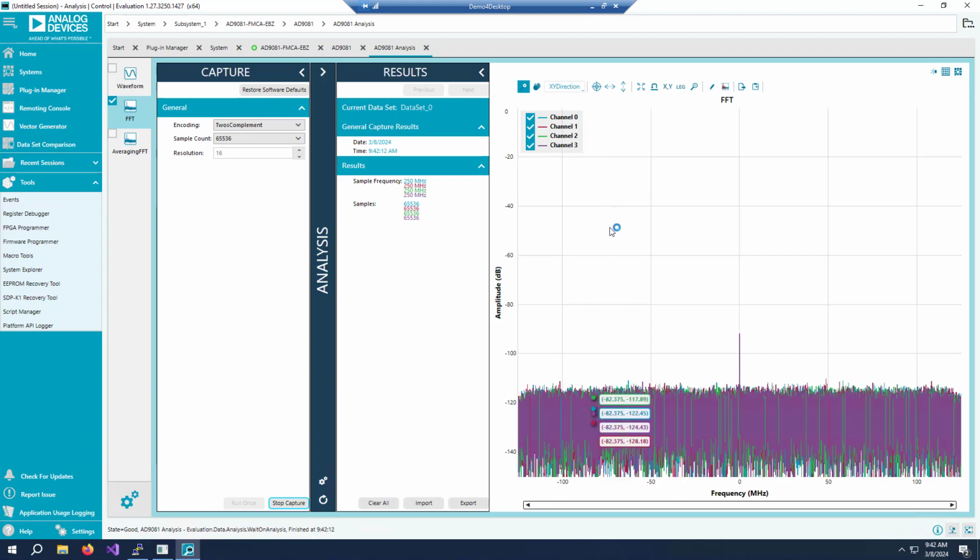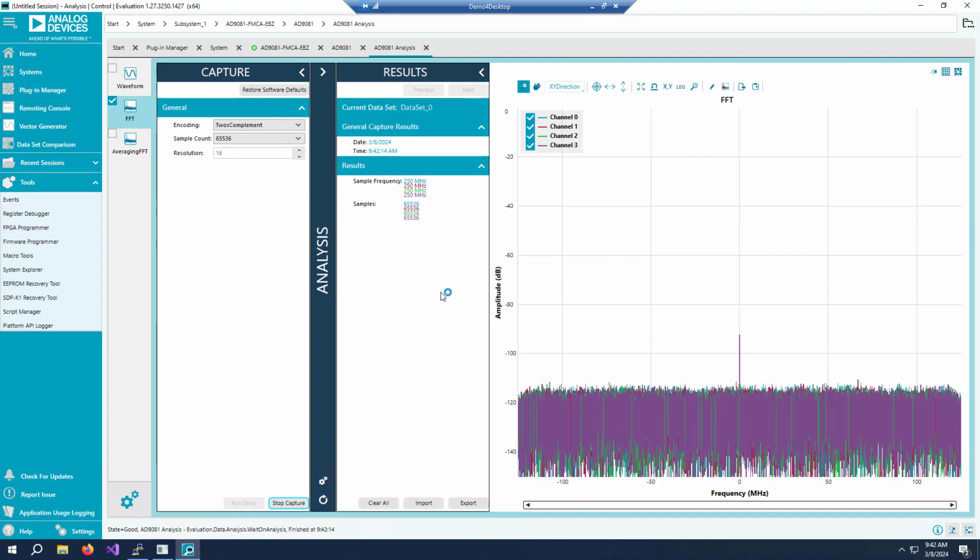They're all running at a gigahertz, and the external IQ sample rate is 250 megasamples per second, so about 200 megahertz usable bandwidth. And the number of samples that each of the channels is gathering is 64K, where the K is the digital 1024 number. Alright, so that's up and running.